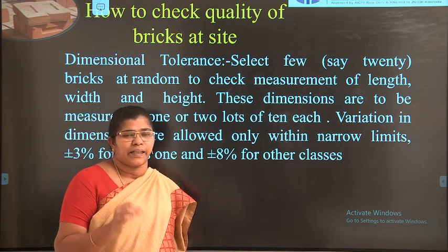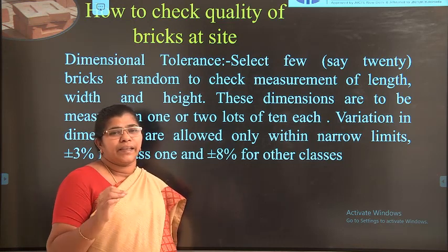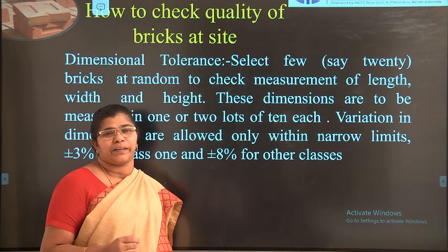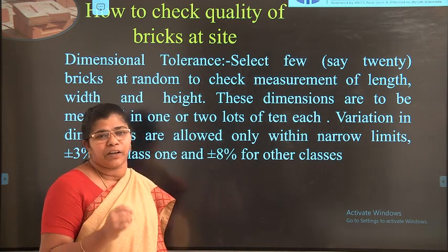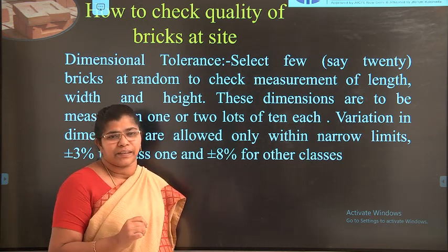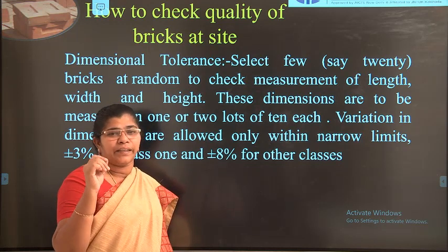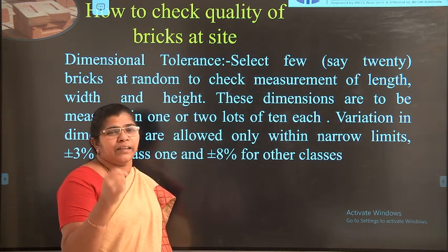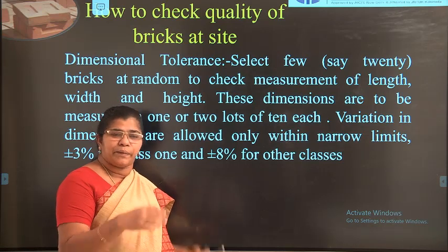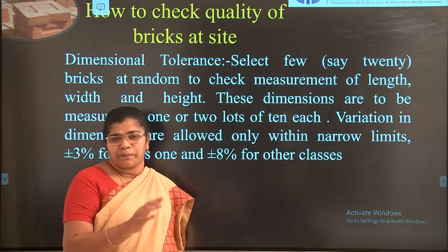How much percentage? Silica of 60 to 70 percent, alumina of 10 to 30 percent, then lime should be there, less than 1% of magnesium, and iron also should be there to impart the red color to the brick. This is for ordinary building material. If the iron and magnesium exceed the limit, then it has a harmful effect. The iron will make the brick yellow, whereas magnesium will make the brick disintegrate.